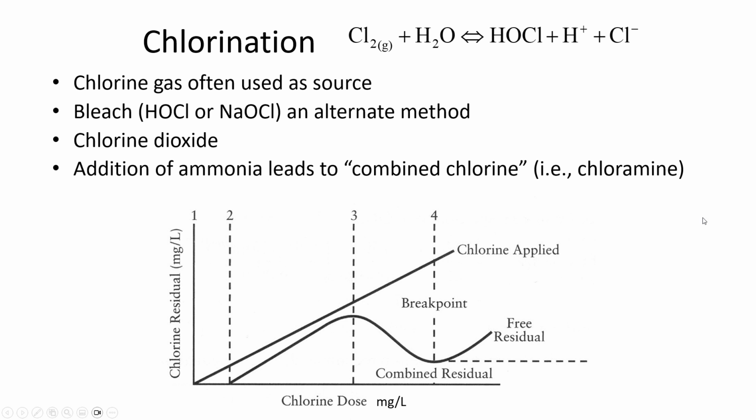It's pretty common in chlorination that you would be adding a certain amount of chlorine and you'd be seeing the concentration going up in the water, but then the concentration would come down as it actually does the work of oxidizing organic material and disinfecting the water. So some of the chlorine that you add is consumed, and then you need to follow through that peak of the chlorine concentration, and you're continuing to add more and more chlorine, and the chlorine concentration is going down, oddly.